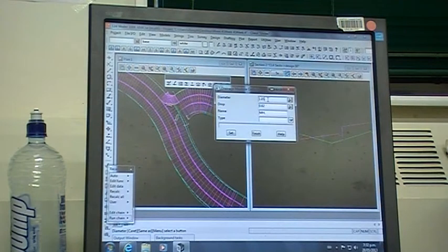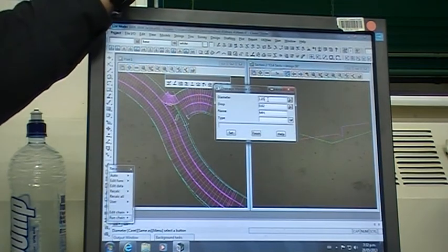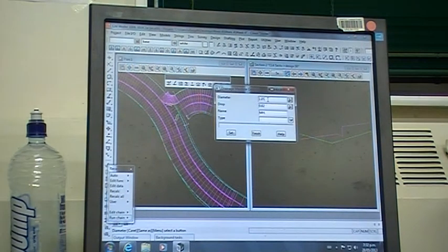There's also, once you pass certain depths, they'll have different standards for, instead of the standard little rungs that people can climb in and out of at a 2 metre manhole, it gets to the point where you need a 1200 or 1500 because we have ladders and platforms, and so at different depths we may have to go up to a bigger size, and certainly if we get into big pipes then the 1050 is not going to work. You can imagine a 1050 manhole is this far across. By the time you put a 600 diameter pipe into it, there's not a lot of actual wall left to fix everything together. So 1050 is our default.